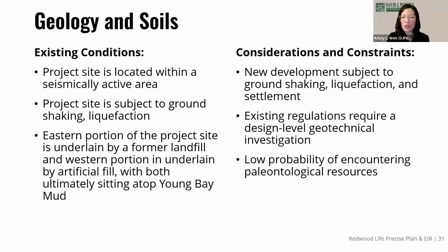Another geology and soil consideration is the potential to encounter paleontological resources, including fossils. Since the site is underlain by fill and Young Bay mud with bedrock starting at 40 or more feet below ground surface, the potential to encounter paleontological resources is considered low.